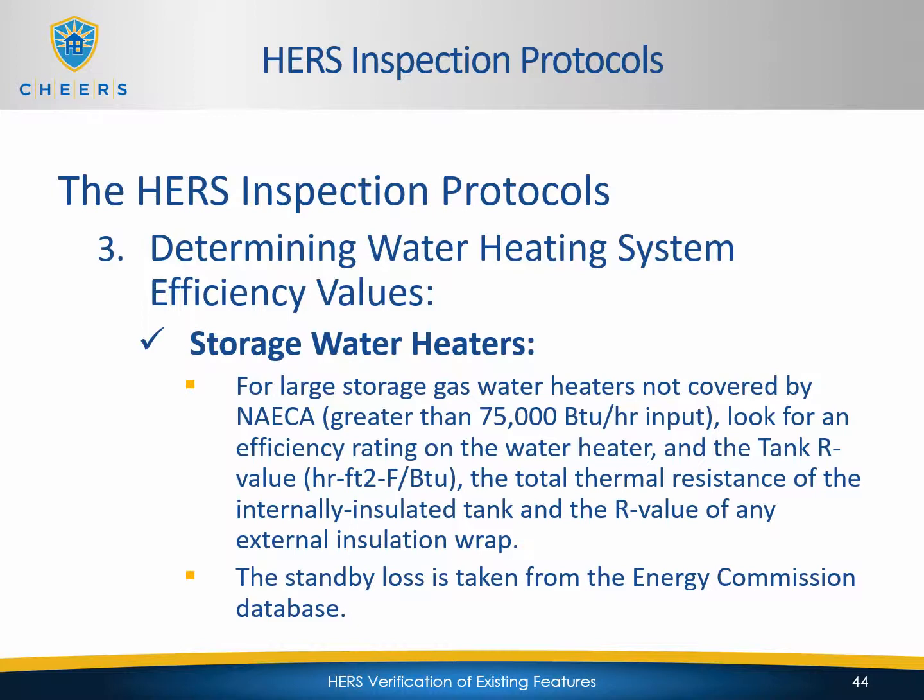For large storage gas water heaters not covered by NAECA, greater than 75,000 BTUs per hour input, look for an efficiency rating on the water heater and the tank R value, the total thermal resistance of internally insulated tank, and the R value of any external insulation wrap. The standby loss is taken from the Energy Commission database.